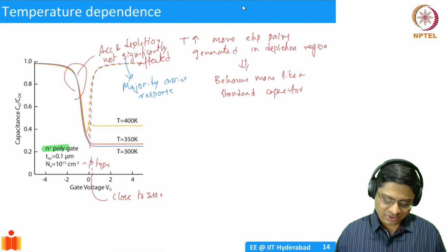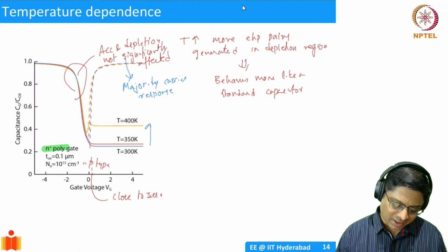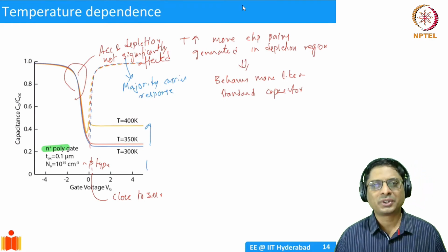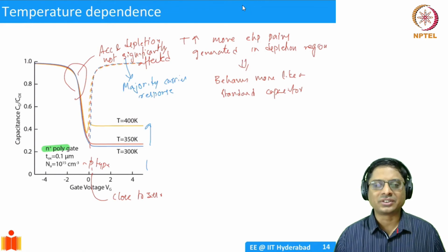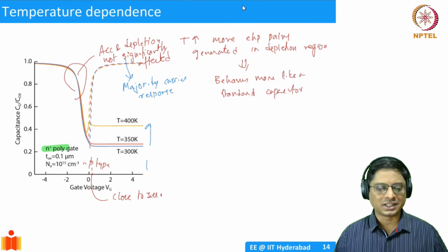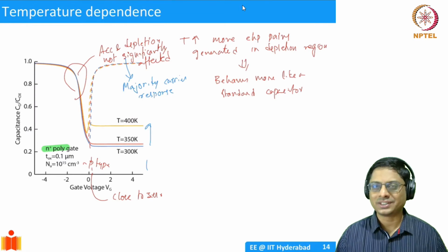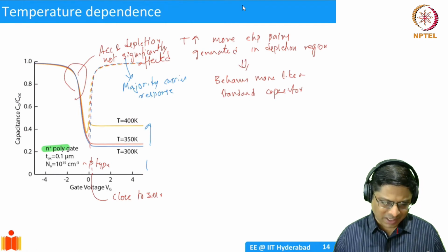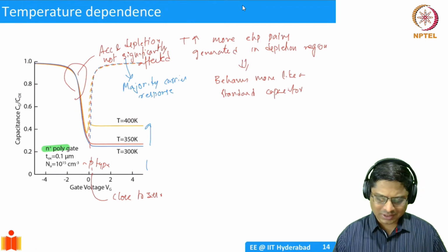Okay, this is how the temperature changes. You see that as you go to higher and higher temperatures, there is a very significant increase in the minority carriers. So that tends to screw up your devices. That's why electronic devices, whenever they get heated, it's not good for their lifetime. They get spoiled much faster. So whenever your laptop or computer is getting heated up aggressively, you have to really think about what's happening, and it might actually be approaching the end of its life. Okay. All right. So this was the parameter dependence that I wanted to talk about.